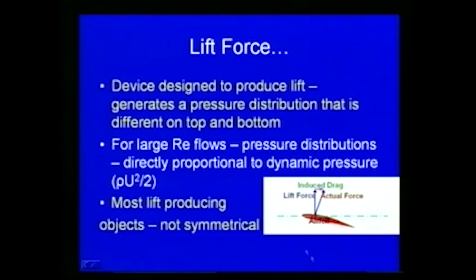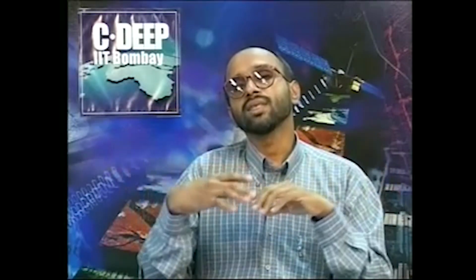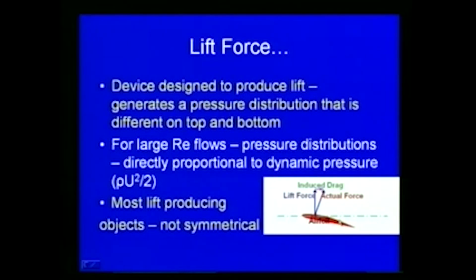Another important thing which we can observe, for example with respect to this airfoil or most of the other designs, is that lift producing objects will be non-symmetrical. We have to design the shape in such a way that it is not symmetrical, so that more lift will be generated. A typical case is this airfoil. When we put it at an angle of attack, we can see that the lift will be more.